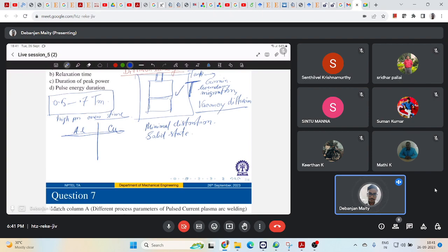So the fundamental principle of the diffusion bonding technique depends on this vacancy diffusion. Initially, let's say your metal surface was like this. It's not flat, right? Atomically, if you look, there will be surface roughness. So let's say initially it was like this, and if we zoom in, there will be material movement from here to here, and those asperities will plastically deform.